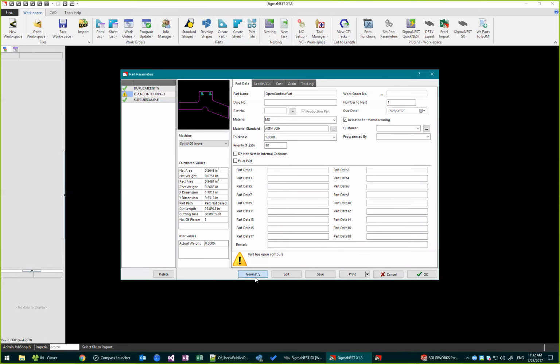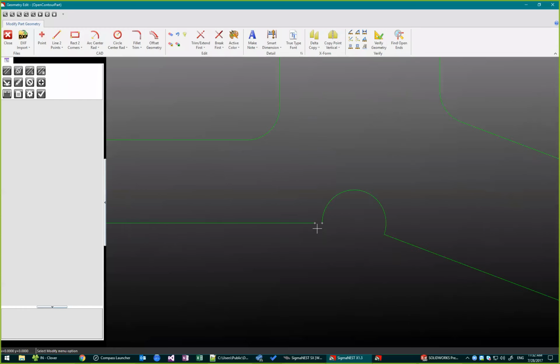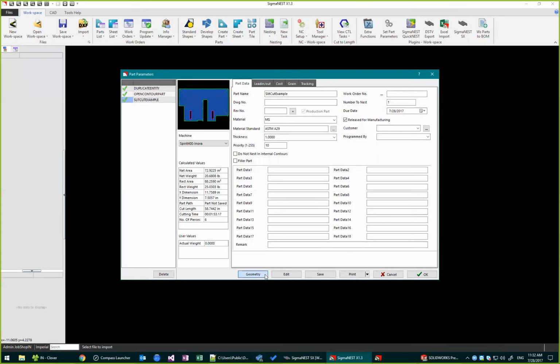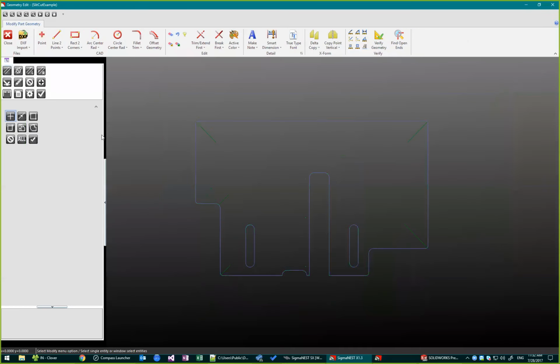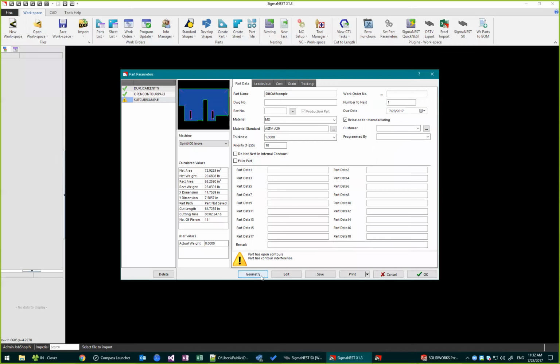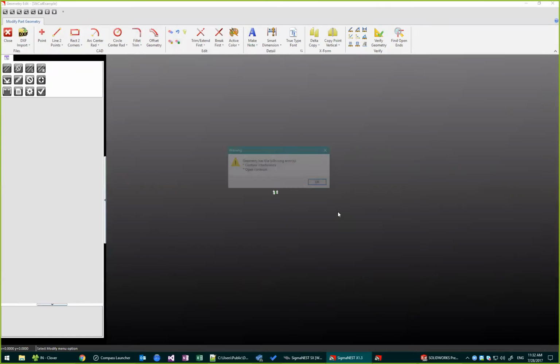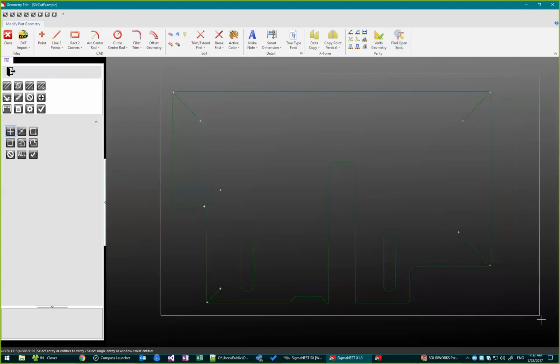The open contour, depending on the kind of open gap that we have here, there are CAD tools to trim and extend and close that up. That's easy enough to find. And the slit cut example, let me change this all to curve cut. And then if I close this, it will complain that those entities are open, they're interfering with another contour. So in verify, I can say, please help me find these.